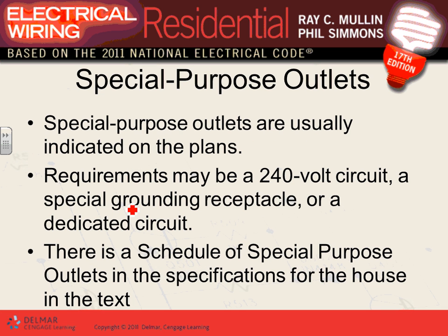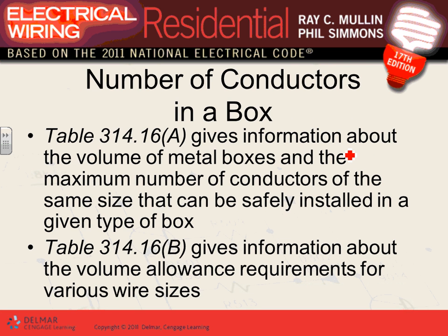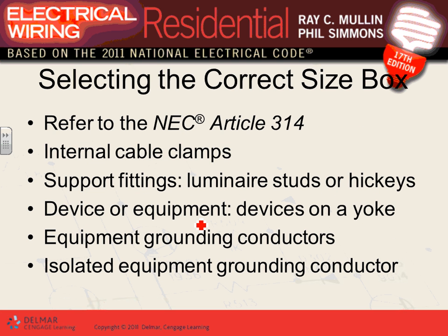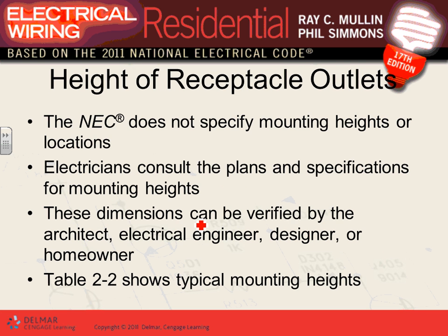So when you talk about a receptacle, special receptacle outlets, and I'm going fast through these. These are the 240. Sometimes they have a 240, 20 amp or 30 or 40 amps for special equipment like ranges and so forth. We'll talk about these, guys. You will see it. Number of conductors in the box. I'm going to go over these 2 tables with you in a second here, in a little bit more detail. And the box fill, I'll get back into that in a second here.